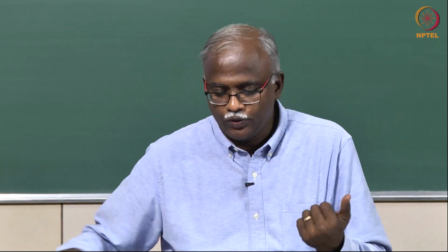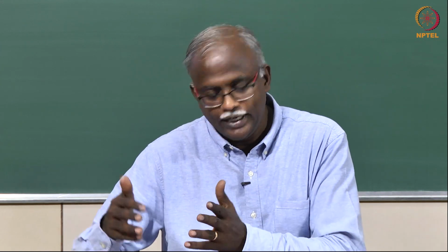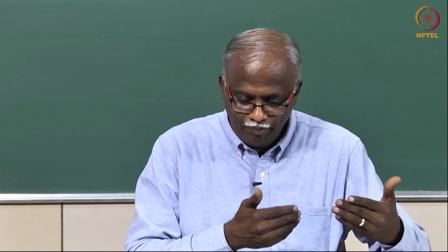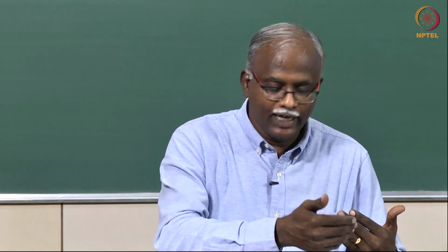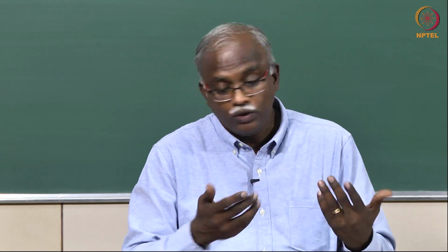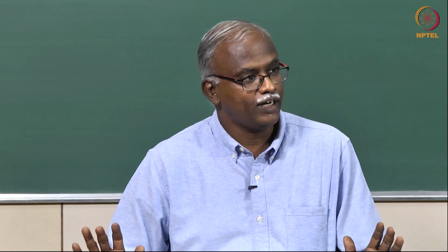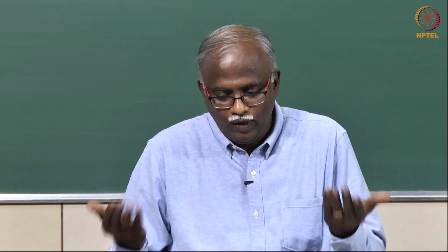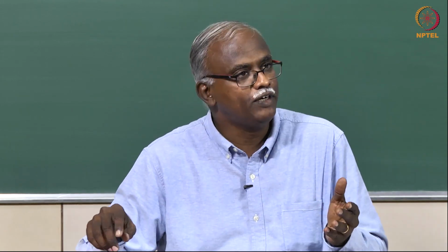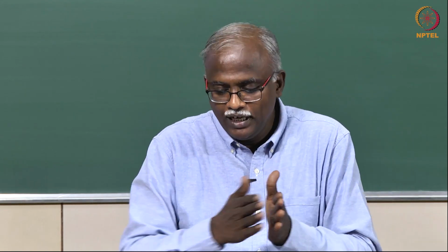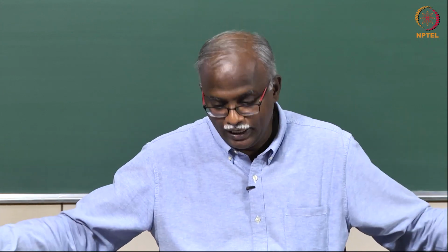So, the very good question. The question is why am I trying to truncate and not try to actually use an ideal filter. See, again we are going back and forth between what can be realizable and what cannot be realizable. So, this green line, a brick wall filter, even in the analog domain I cannot realize it. The way to visualize why is that this is a filter that will be infinite in terms of time, and it is non causal.